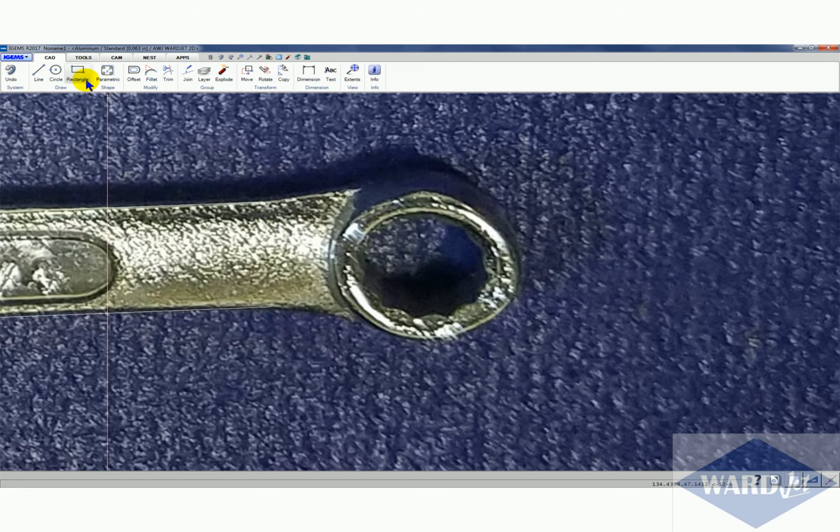And then another trick you could do is under the draw menu, you've also got this sketch command, which is essentially like a pencil. So you can click on this and sketch starting from the endpoint of here, for example, and then you just hold your left mouse button down, and as long as you hold it down, it's just going to draw this little line there.